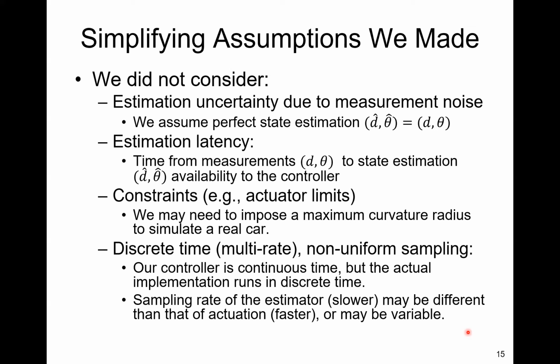There is also estimation latency, the time from the measurement to the state estimate being available to the controller. This is the execution time of the filter algorithms, and also constraints such as actuator limits. We may need to impose a maximum curvature radius to simulate a real car. A real car can turn at a maximum angle. You cannot arbitrarily turn at very large angles.